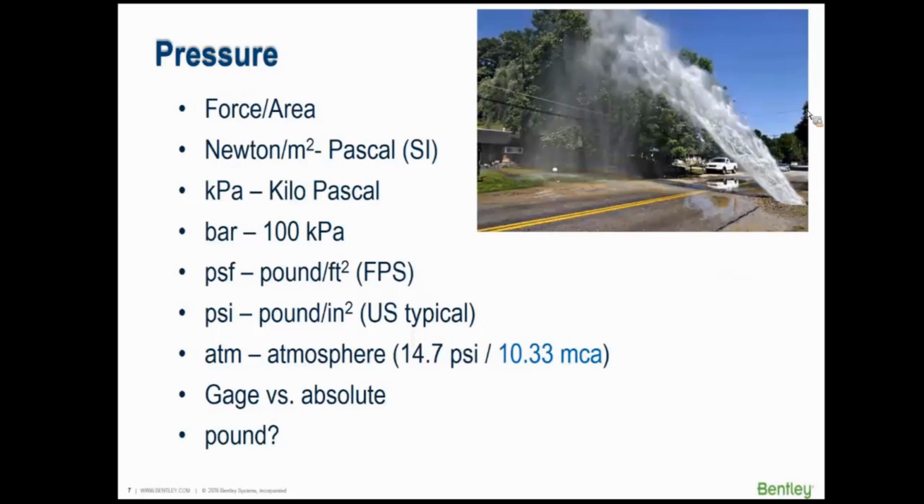Okay, so if we have those numbers, then we also can talk about pressure in terms of atmospheres. An atmosphere is 14.7 psi because that's what you'll feel if you're just standing outside around sea level. That's the amount of pressure from the air above you. So how many times the air pressure is the atmospheric pressure? But pressure gets even more complicated because are you measuring the pressure relative to the atmosphere or are you measuring the absolute pressure? That is the pressure including the atmospheric pressure.